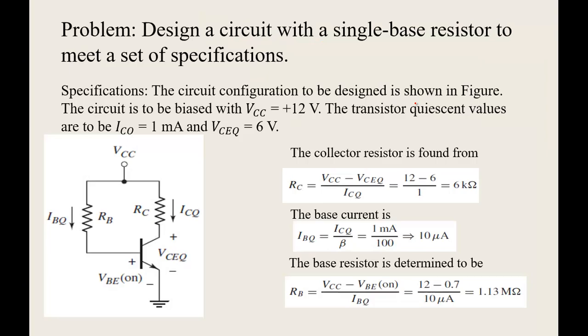Fine. Okay. Next one is basically using a fixed voltage regulator. So again, same principle. Instead of having three different supplies, you have only one supply and the other one is grounded. So apply KVL here and apply KVL here and determine your currents and voltages. That's how we basically do. Okay, so VCC is equal to 12 volts here. And this is ICQ. ICQ is almost 1 milliampere, and VCEQ is 6 volts.